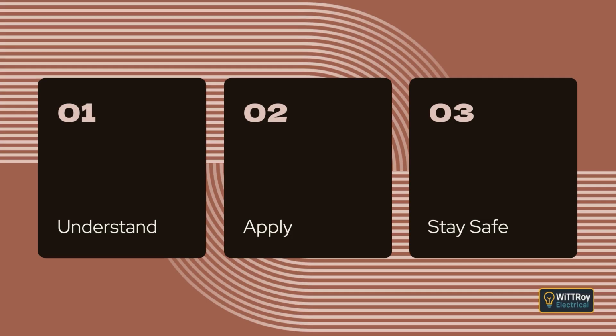Clause 3.8.3 Exceptions and special applications. This clause explains where the identification rules of clauses 3.8.1 and 3.8.2 do not have to be followed. Clause 3.8.3.1 Protective earthing and equipotential conductors. A bare or aerial conductor used as a protective earth does not require green and yellow identification.